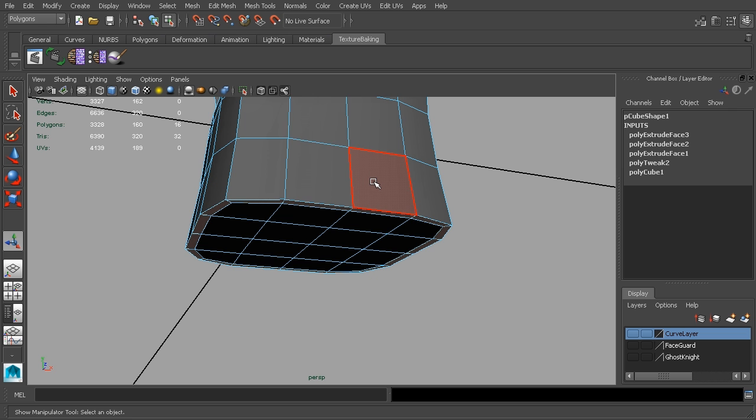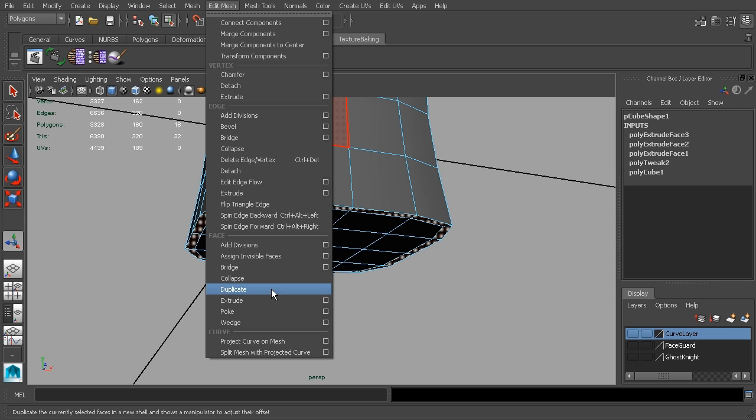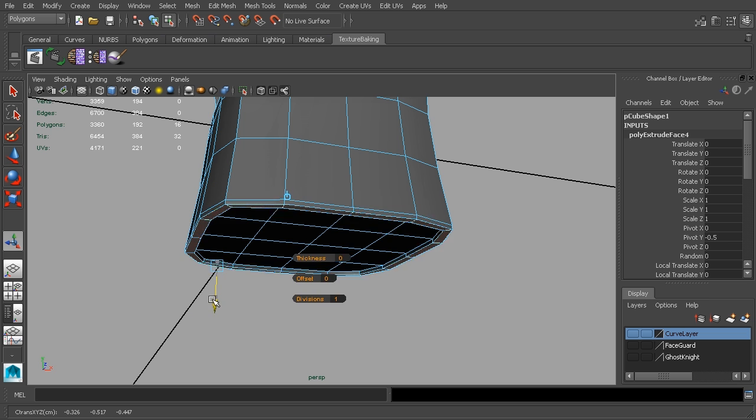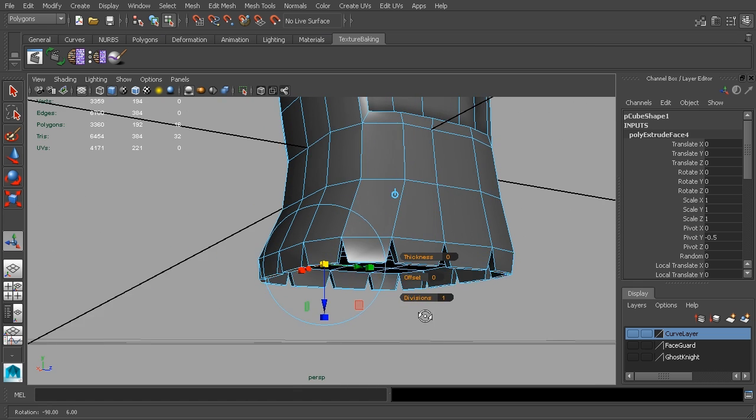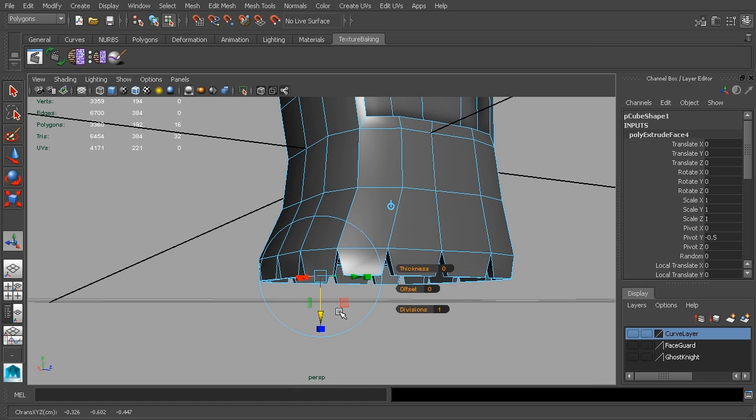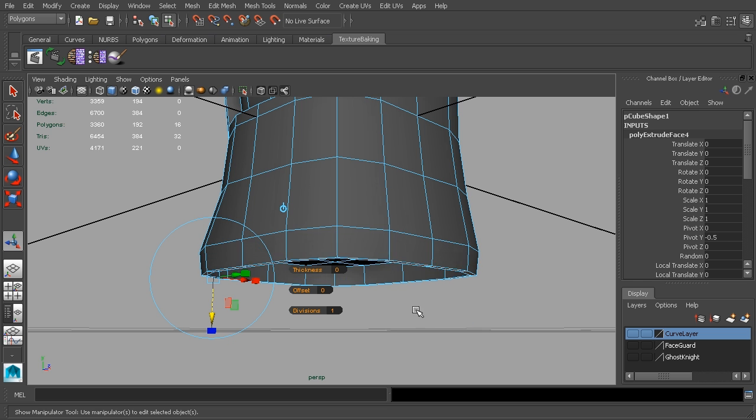And so what we can do is simply go to face, extrude, and we can pull this down. And then with that still active, we can hit Control Shift, right click, and we can toggle keep faces together. So if we toggle that off and then scale this down, you can see that those are actually separated. Okay, we're still active. We can toggle that back on.